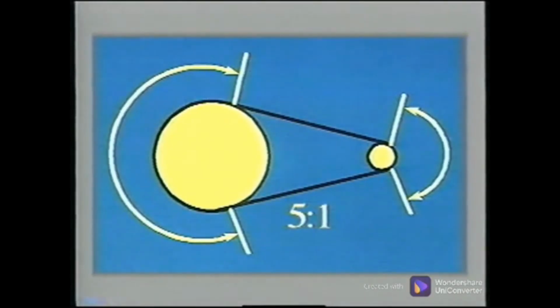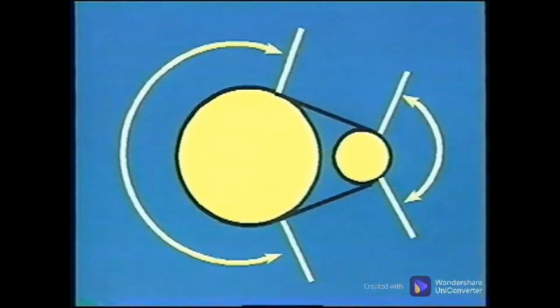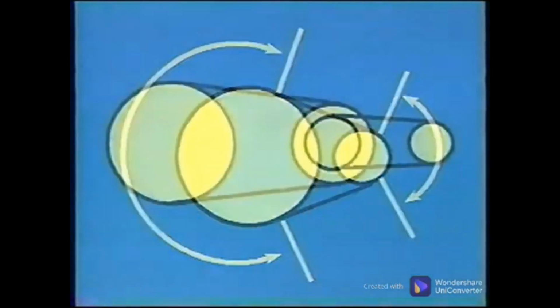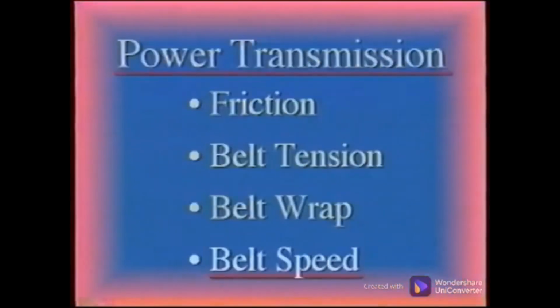A ratio greater than 3-to-1 is not recommended. A ratio of 3-to-1 has acceptable belt wrap when the center-to-center distance is great. But if the sheaves are close, the belt wrap is substantially reduced, decreasing friction and increasing belt slip. If a higher ratio is required, use a stepped drive with an intermediate shaft.